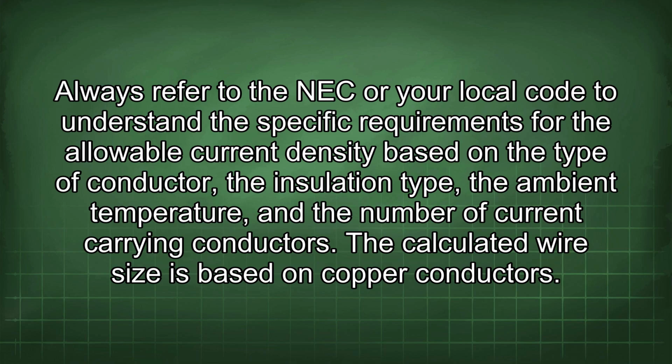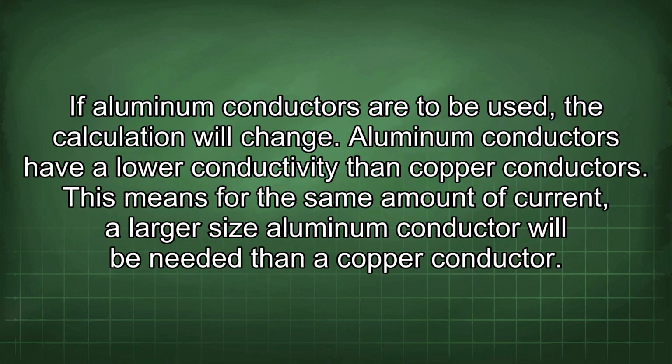The calculated wire size is based on copper conductors. If aluminum conductors are to be used, the calculation will change. Aluminum conductors have a lower conductivity than copper conductors. This means for the same amount of current, a larger size aluminum conductor will be needed than a copper conductor.